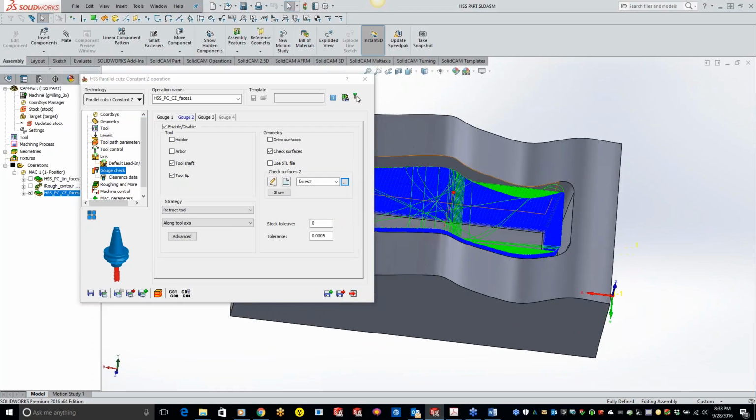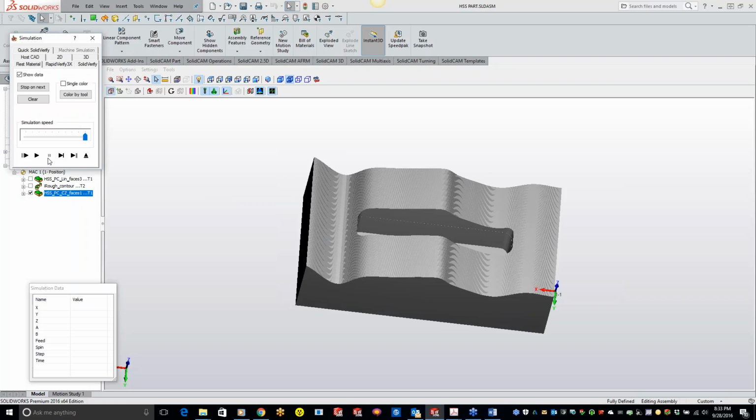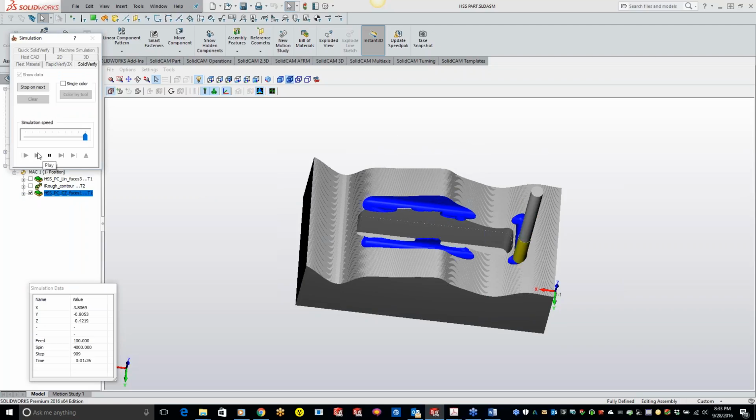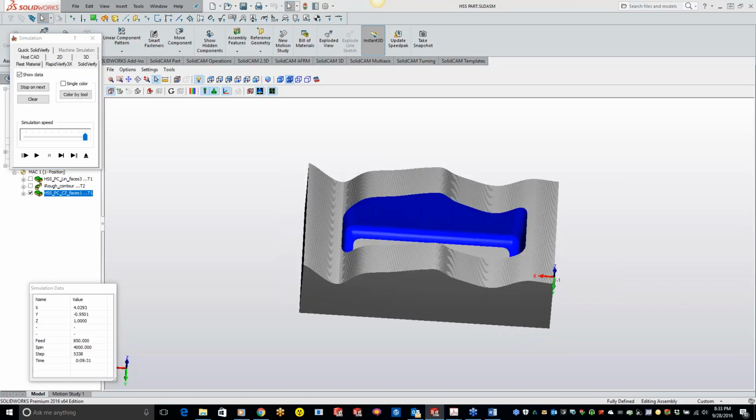And now we can see that we're not, let me just do a simulate here. And since we're working on that tapered wall, I did the iMachining out to a certain spot. But you'll see we're taking one heck of a load on that cutter coming down. We actually have the little islands hanging up there. So what I'm going to do here, once it's finished up, all right. So obviously that's way too much of a cut, especially if we're cutting anything other than foam or wood.